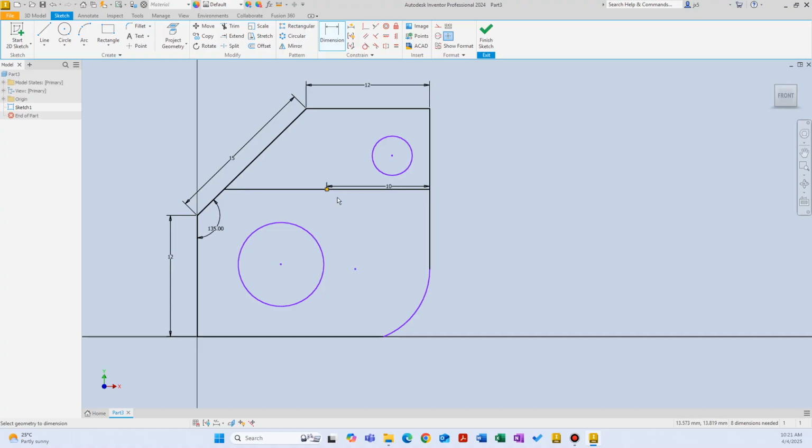It's got a location, a designated spot in space. But I don't frequently see a line being dimensioned like that, but you never know. I just wanted to show that. But again, we can click on the full length of the line and assign, let's say, 20 millimeters. Now that line is also fully defined. Let's click OK and get out of that command.